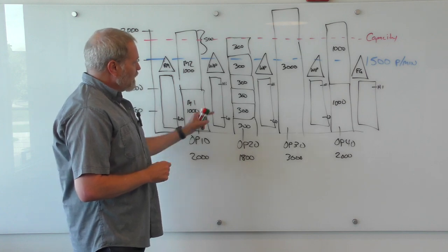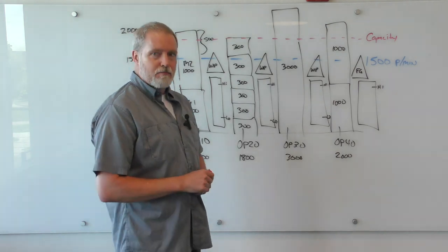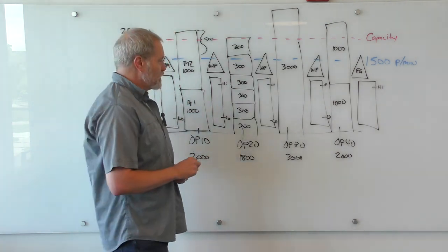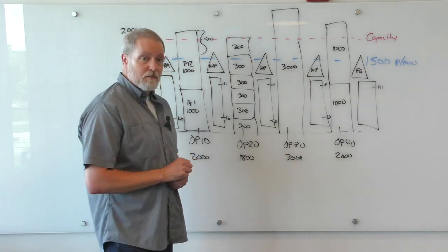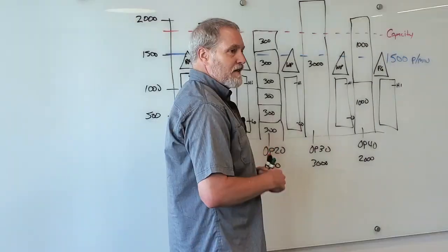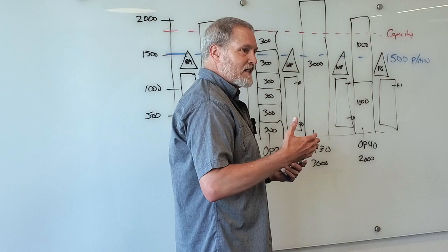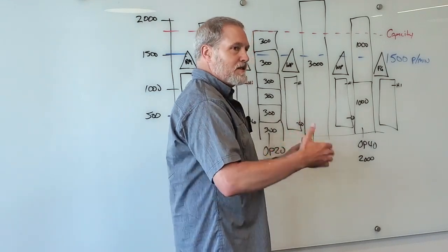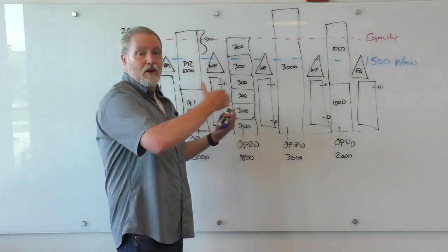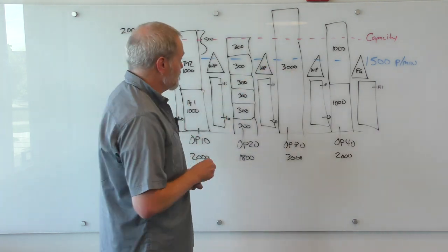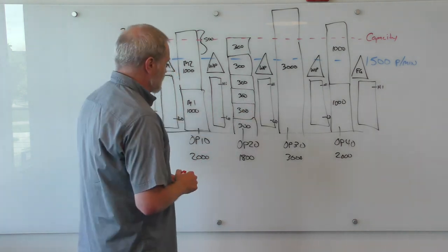Okay, one thing on inventory is just to say, well, what are we aiming for? A number of parts or units, or is it time? Typically people like to understand both. You have to size your conveyor or your queues for a number of parts, but you also ultimately want to relate that back to minutes. So it's how many minutes of downtime can I have on one of my operations without blocking or starving another operation in the process. And so each one of these will be sized according to those needs.